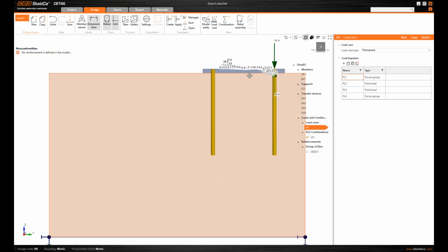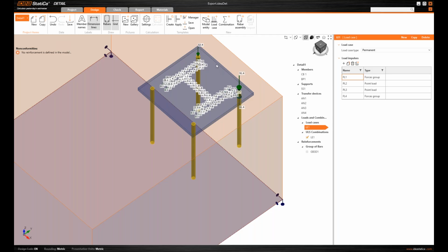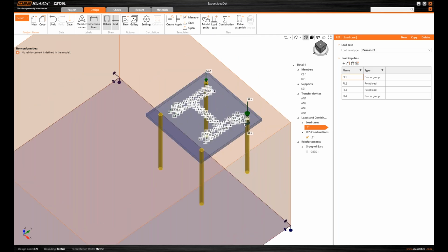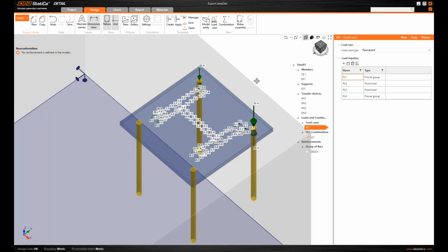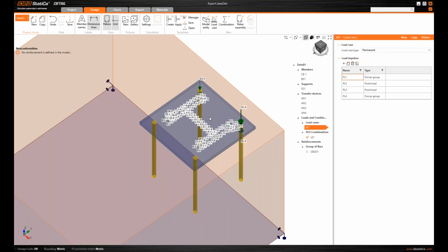When we modeled it this way, there will be no discrepancies in the anchor forces. It's important because there is a difference between the models. In the connection application, you have nonlinear material for the base plate, and there is also a portion of the column modeled, which is not here in the detail application. So again, this is the way to ensure that the forces in anchors are exactly the same as in the connection. This is the one imported load case.